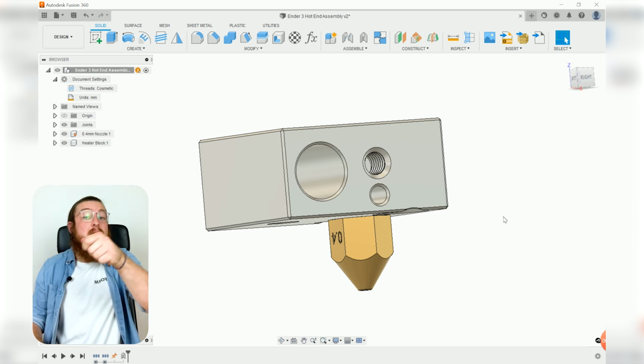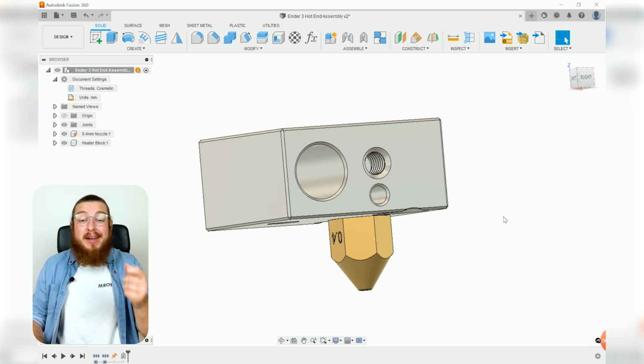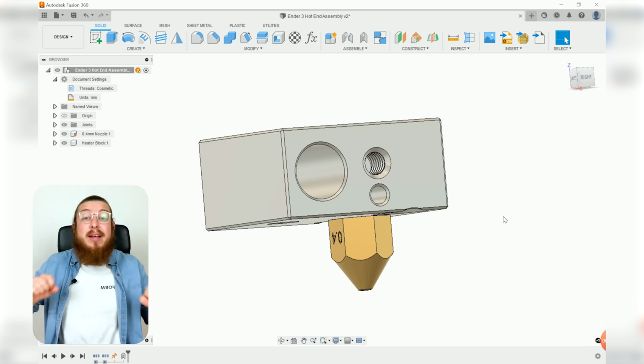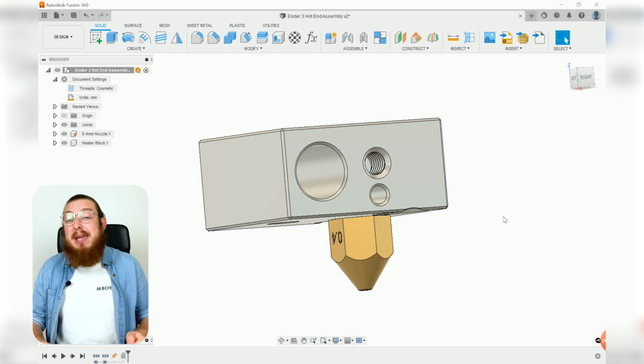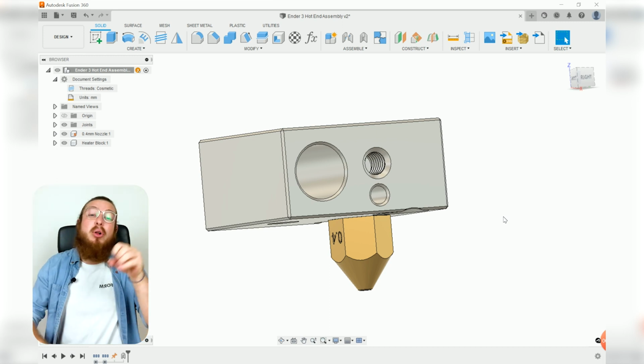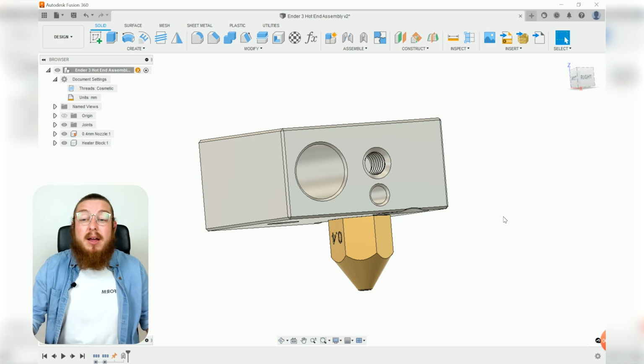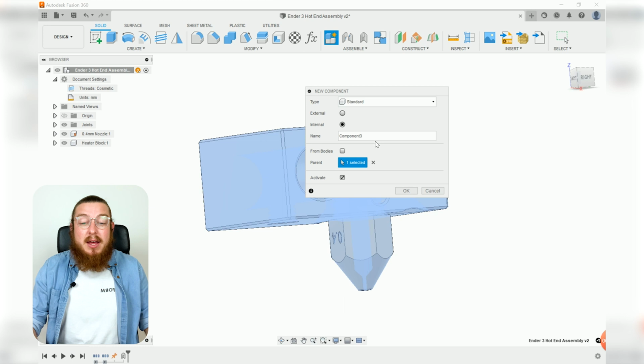It can be made of different metals or usually ceramic, anything that can handle the intensely high temperatures. If you actually take the heating element out of the heater block, which pulls away a lot of the heat, and turn your printer on, it will actually start to glow red. It gets that hot, and so it needs to be kept inside this big housing that can pull away as much heat as possible.